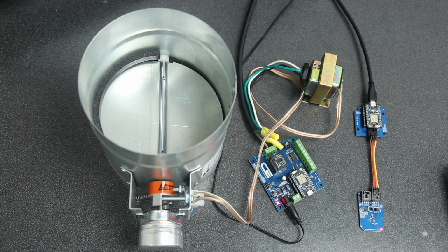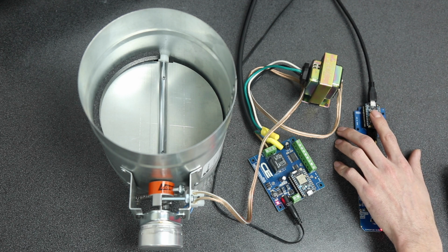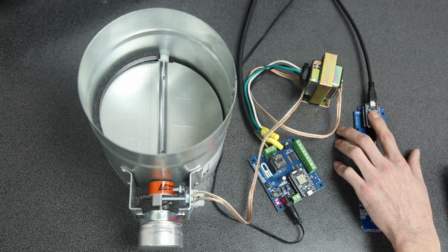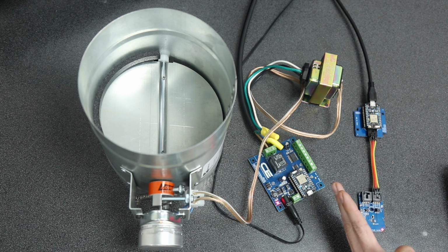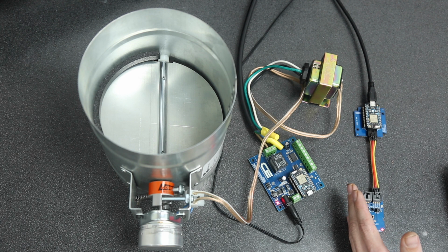So in the firmware running in this temperature module, this is actually where most of the work is done. What we're doing is we're reading the temperature. We're setting a set point temperature that we want to keep the room set at, so maybe we're just going to set this room to 60 degrees. We can also program a temperature swing. Most of your common thermostats have a 1 degree temperature swing.